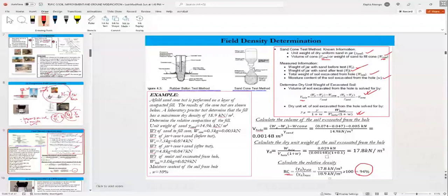Okay, you may use admixtures, but what if admixtures are not specified? It's just simple: rework the place, scarify it and then rework it through.